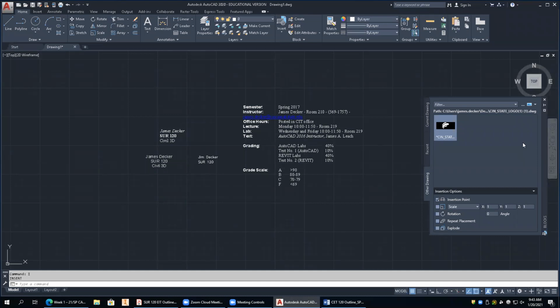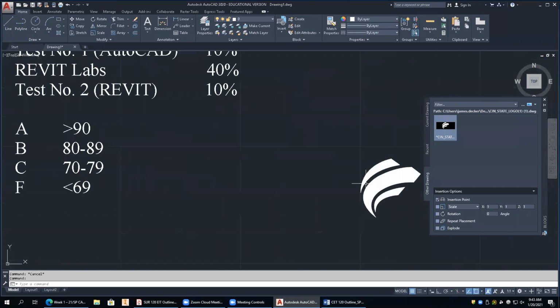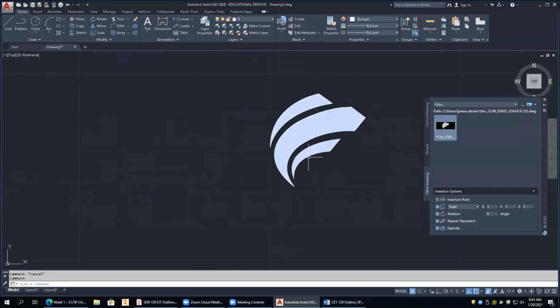Then when you click on that, you can just drag it into your drawing, and there it is. So when this guy's in there, by the way, don't explode him. But there's the grip that you need to use to center it with. That grip right there, that's your centering grip. I'm not sure what those other grips are, but that's the one you want to use.